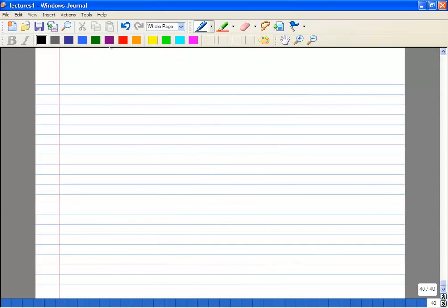What is step number 3? LS is LP times square root of 1 over 1 plus Q squared. So it's going to be slightly lesser than LP, because in this case Q is very low, right? You see that LS is fairly different. In this case it happens to be 5.75 nanohenries. So obviously if the Q was higher, it will get closer and closer to LP.